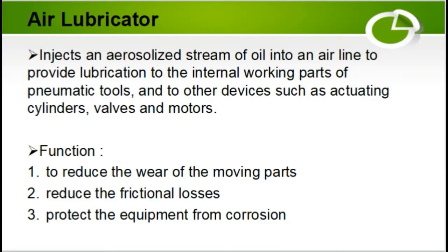Air lubricator. Air lubricator injects an aerosolized stream of oil into an air line to provide lubrication to the internal working parts of pneumatic tools and to other devices such as actuating cylinders, valves, and motors. Okay, the function of air lubricator is to reduce the wear of the moving parts, reduce the frictional loss, and protect the equipment from corrosion.